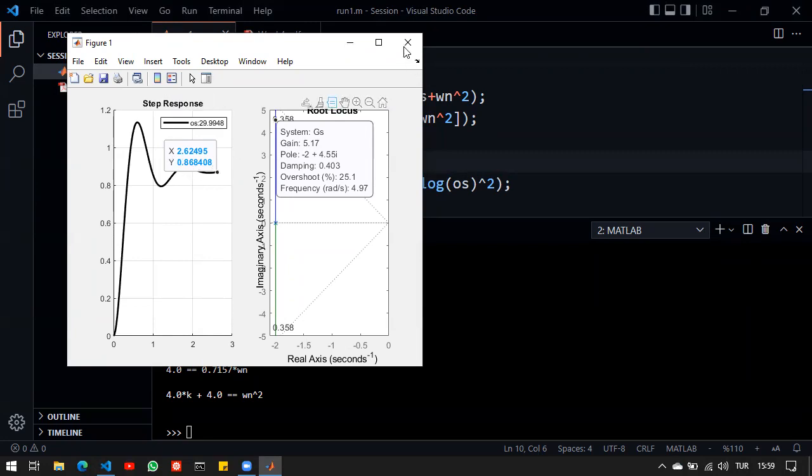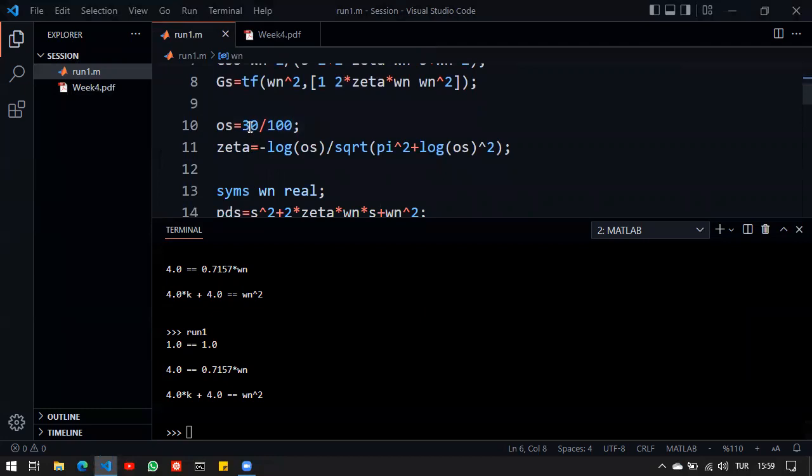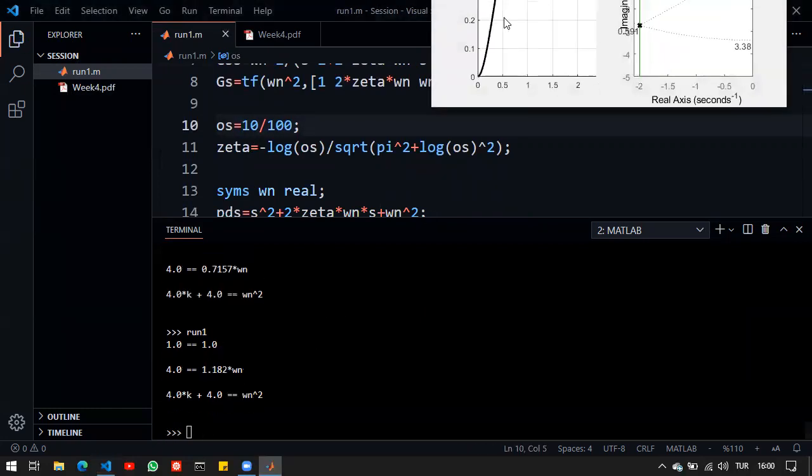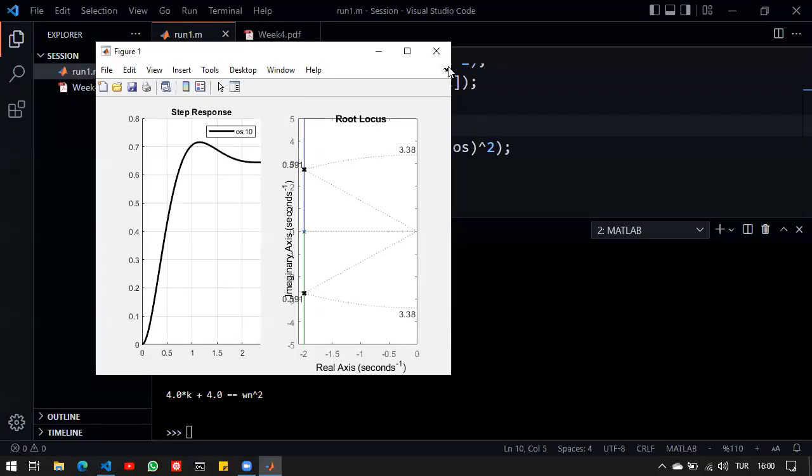So there's a cost there. Now, that's all I can achieve with a P-type controller. Let me again show the solution here. That's the best I can do here. It has exactly 10% overshoot as expected. I have a steady state error here. The root locus looks like this, and I'm stuck on this line. So the settling time, for example, cannot be changed with a P-type controller.